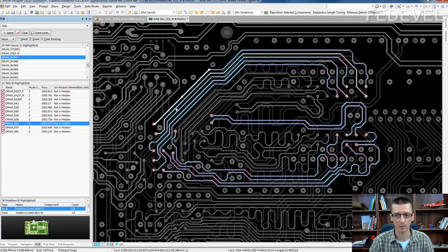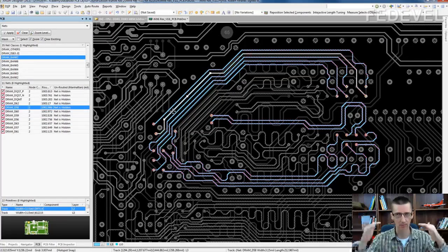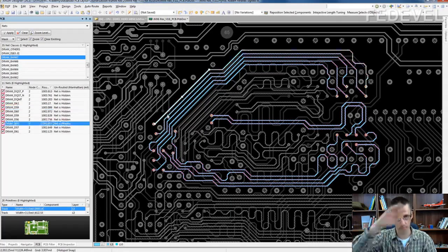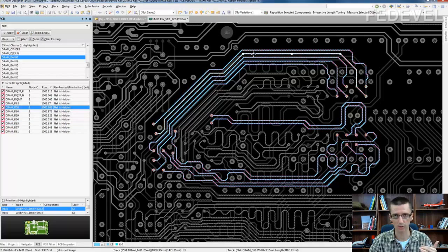Then I continue with the second signal from the outer layer. I draw it close to this signal, which I did, and if this signal is shorter, usually it is shorter, I add a wave to make it a little bit longer than this signal here.